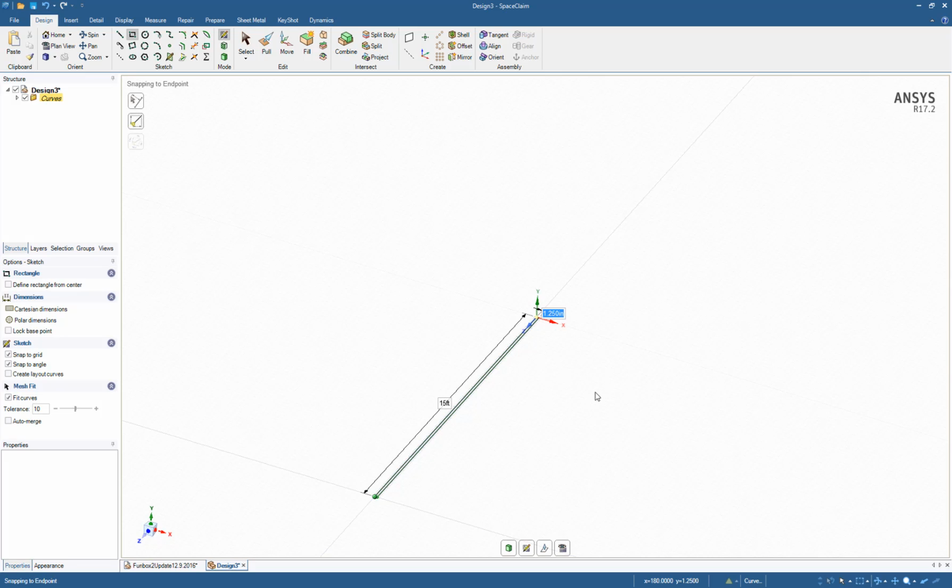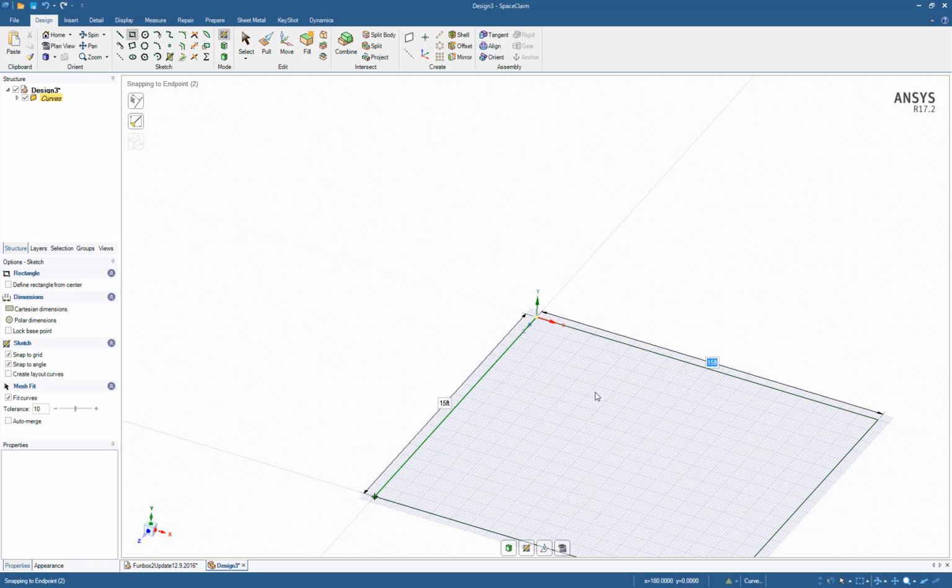Notice with that done, the other text box for the other dimension in the X direction is now highlighted as if it's waiting for me to type that number in as well, which is exactly what I do. So I'll say 15 feet there, and I'll say enter, and now I can still make changes if I want because the text boxes are open.